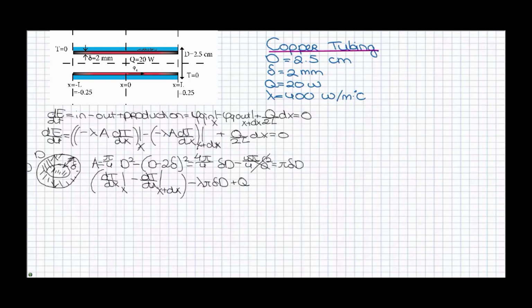We can solve the equation by using the boundary conditions, and the boundary conditions are, if you think about it, very logical because the temperature gradient at x is 0 in the sketch is 0, because the production in the middle is exactly the same. The heat will only transfer from the middle of the tube to the ends of the tube and not transferring to the middle of the tube, so it has to be 0 there. And we know that at the ends the temperature needs to be 0.